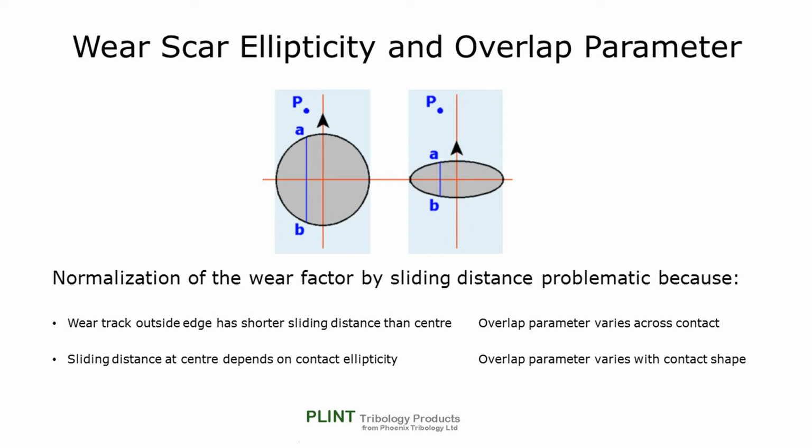In addition to this, a widening of the nominal contact area may enable more debris entrapment in the interface, and the longer the contact, the greater the sliding or rolling distance of an entrained abrasive particle. This may result in a higher three-body abrasion component. These issues do not exist with a line contact, of course.